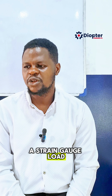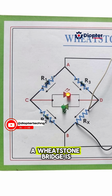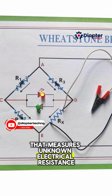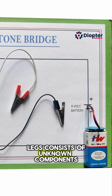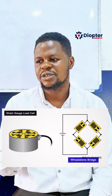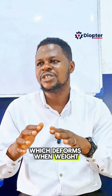A strain gauge load cell is made up of 4 strain gauges in a Wheatstone bridge configuration. A Wheatstone bridge is an electrical circuit that measures unknown electrical resistance by balancing 2 legs of a bridge circuit, where one of the legs consists of unknown components. The Wheatstone bridge circuit provides incredibly accurate measurements. The strain gauges that are in the Wheatstone bridge are bonded onto a beam which deforms when weight is applied.